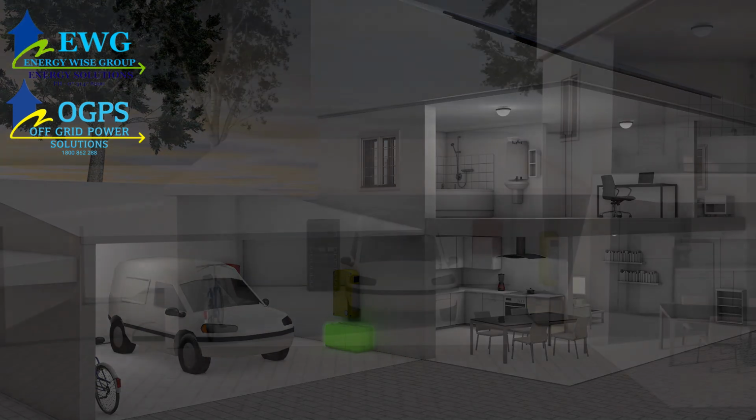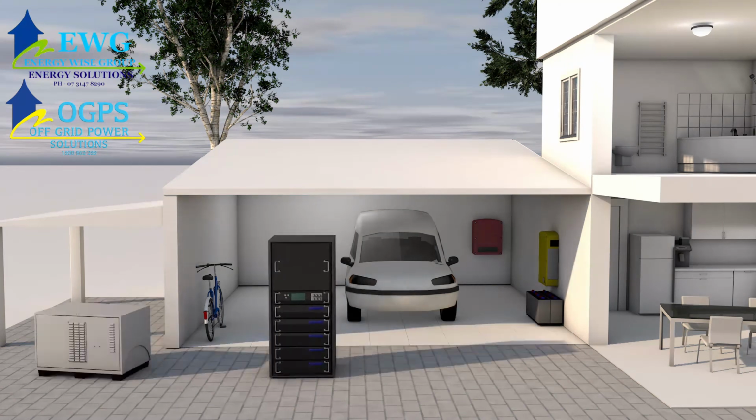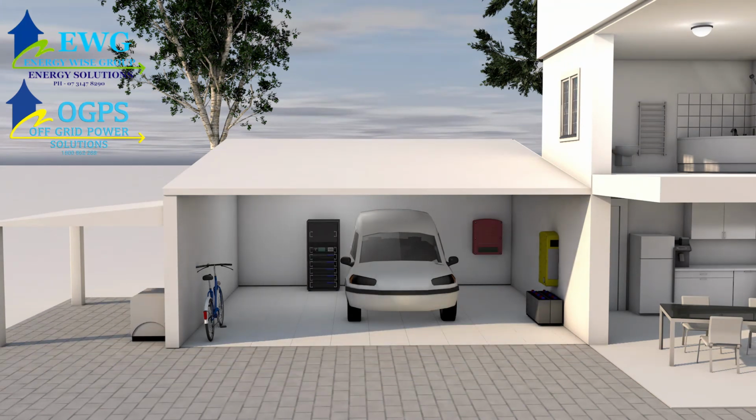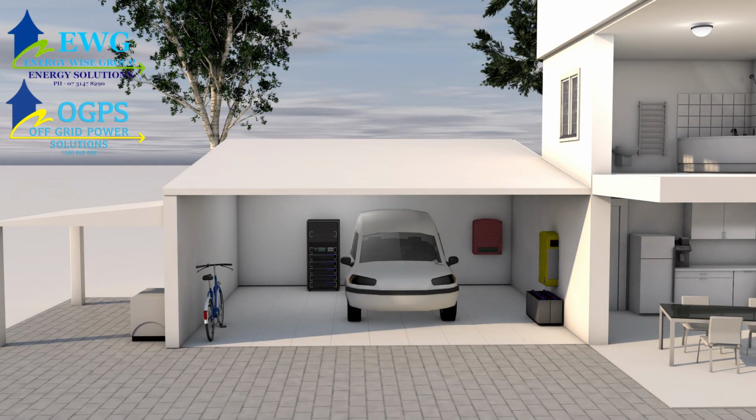About the battery cabinet or housing. Each battery, its location, and its placement inside or outside will determine the cabinet design no matter what the technology. Batteries should be protected from the elements. Good, clean, dry, moderate temperature with good cross-flow ventilation. In some cases, a small fan may be needed inside the housing that is controlled by a temperature thermostat, or in extreme cases, a cooling system may be considered.